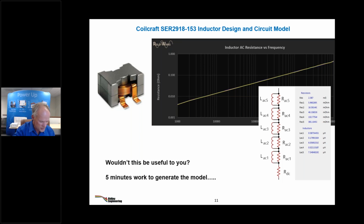If I was designing this inductor, I would not gap it right in the middle because it's next to the windings. So there is going to be gap loss. Do we account for that? No. My advice is put the gap where it doesn't cause loss. And it's not hard to do. You just do an EI core here and you shift the gap down to the end. There's plenty of room in this winding, and then you shift the winding down to the bottom, and there is no gap loss.